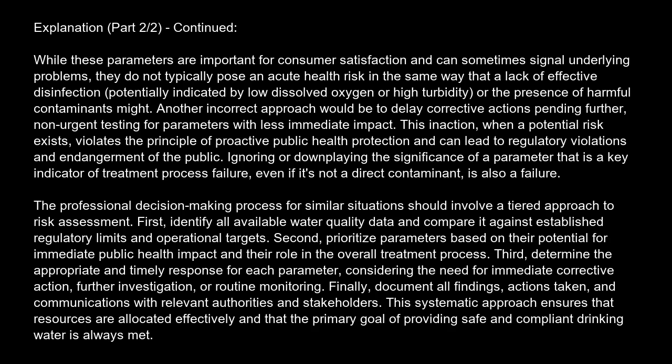The professional decision-making process for similar situations should involve a tiered approach to risk assessment. First, identify all available water quality data and compare it against established regulatory limits and operational targets. Second, prioritize parameters based on their potential for immediate public health impact and their role in the overall treatment process. Third, determine the appropriate and timely response for each parameter, considering the need for immediate corrective action, further investigation, or routine monitoring. Finally, document all findings, actions taken, and communications with relevant authorities and stakeholders.